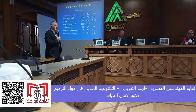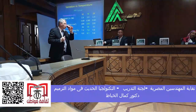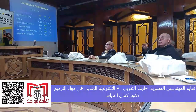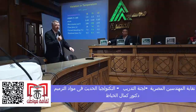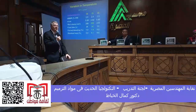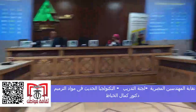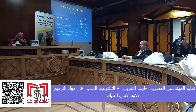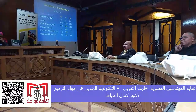Next. Sorry for the interruption, but I think there is a contradiction between what you said and the equation you showed us, where the viscosity was in the denominator. Yes, so you want to reduce the viscosity. V max is equal to 1 over viscosity. So when I decrease it, the velocity increases. But you said you want the viscosity to be low. Yes, low, and also the speed. It's the shear rate. The shear rate is dV/dx.